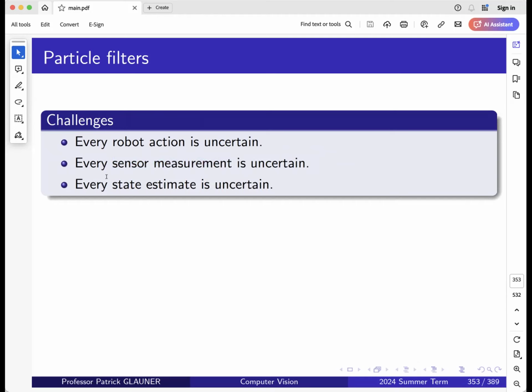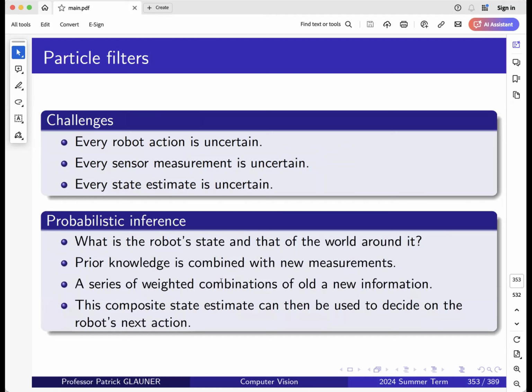And in fact, we are doing a state estimation. We're now looking at a filter method that we call a particle filter. You've learned about the Kalman filter last week, and today we are looking at the particle filter, which is a different state estimator, specifically helpful for localization in maps. Later, if you want, we can also contrast it a bit to a Kalman filter, but it just serves a different purpose.